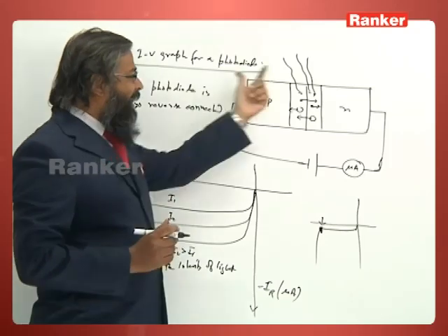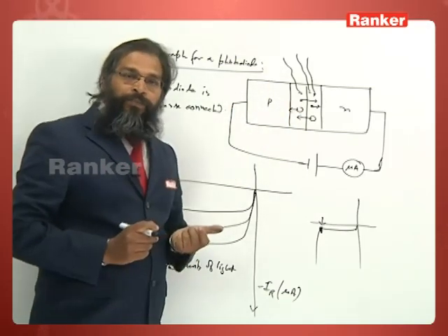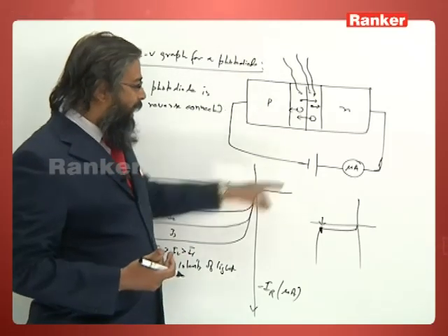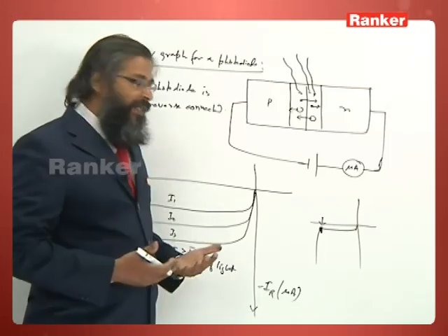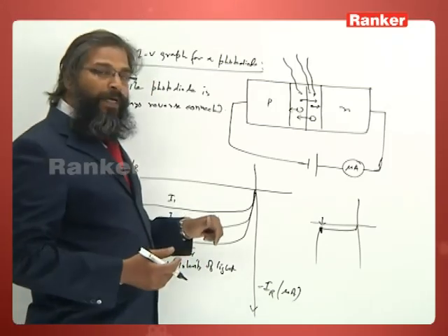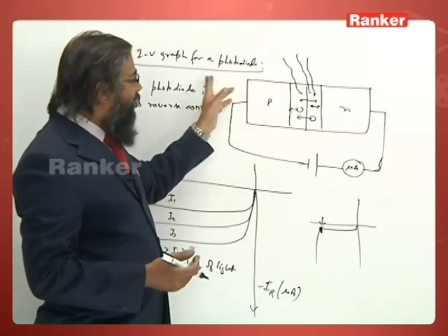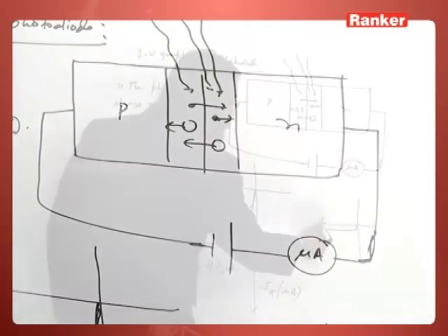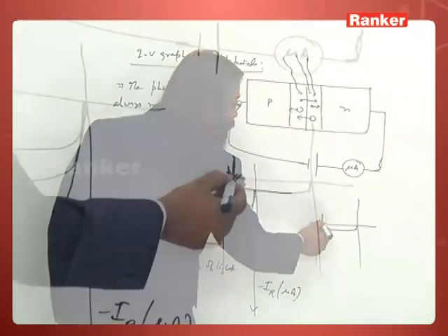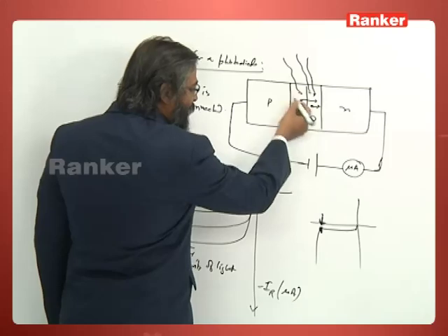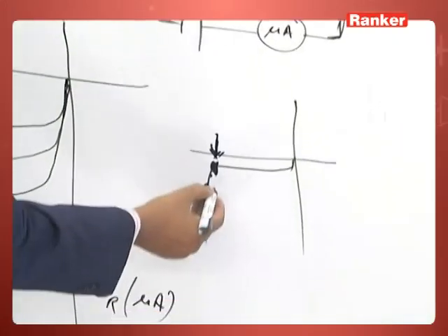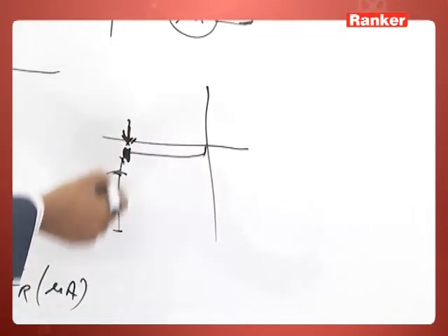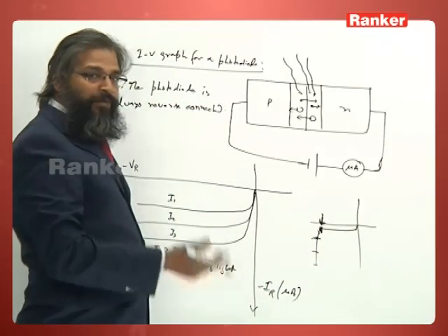So this is the normal photodiode where the current is low and that is a saturation. Sometimes we require a special type of photodiode in which we want a current gain also. That means when the light falls, the current is very large, we want a current gain. That is a special purpose photodiode called the avalanche photodiode, which is reverse biased so that the reverse biasing is at this stage. So when the light falls, the current becomes large, and here the breakdown region is this, so here current gain will take place.